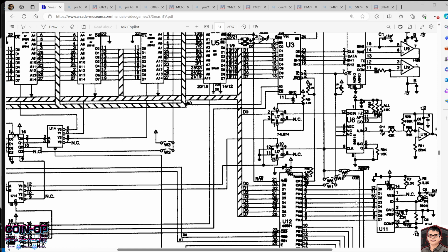Sure enough, what I found was when I had implemented it and started up the game, I was getting sounds. The speech is produced by the 55516 chip, or the 55564 chip, which is right here. I'm sorry, not sound effects, but speech. And then the synth is produced by the 2151 in accordance with this DAC. This DAC is actually integrated in Jotego's 2151, so I didn't need to wire that differently or externally. It's already embedded in there.